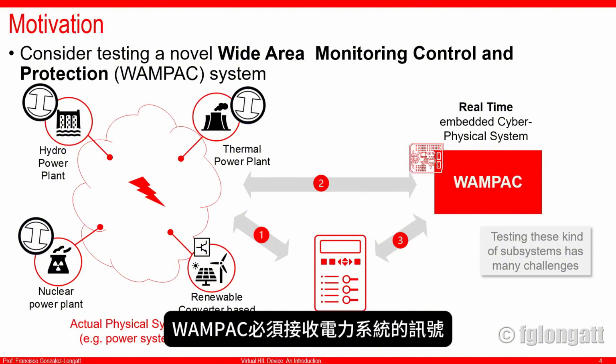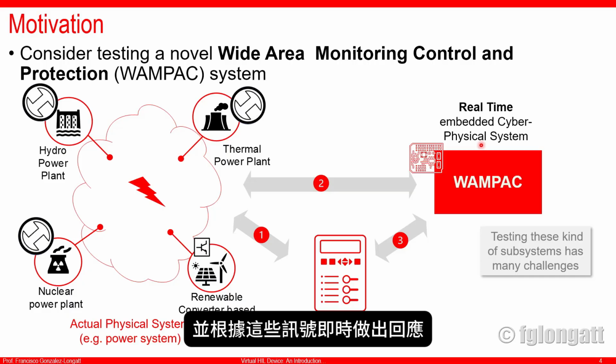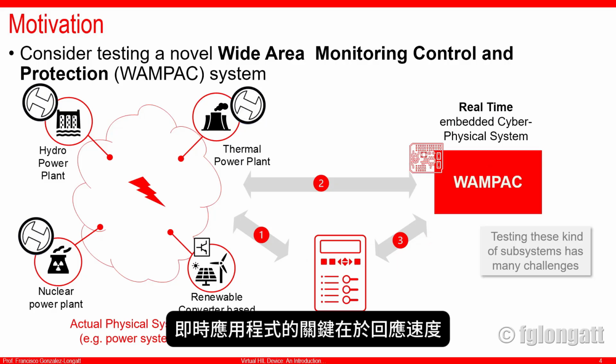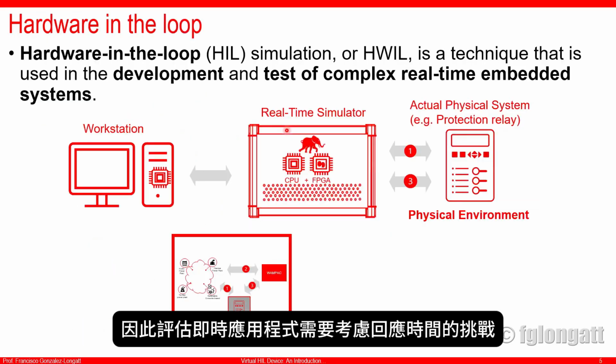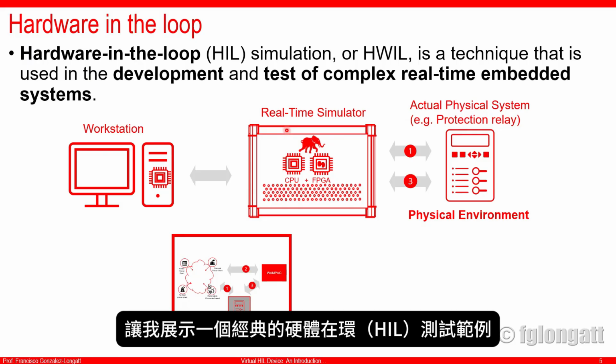But imagine the following. Imagine that we are interested in developing this WAMPAC, but at one stage of the development process, we would like to know what response the physical protection relay has when this WAMPAC is working with the power system and closing the loop with the physical relays. Well, to solve the complicated situation related to testing this kind of cyber physical system, hardware in the loop simulation is very important.